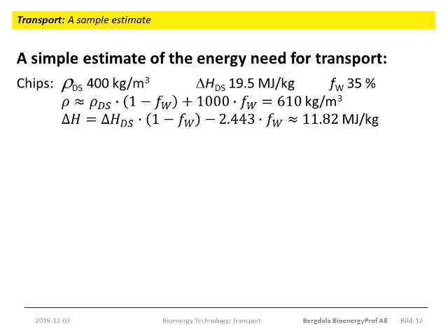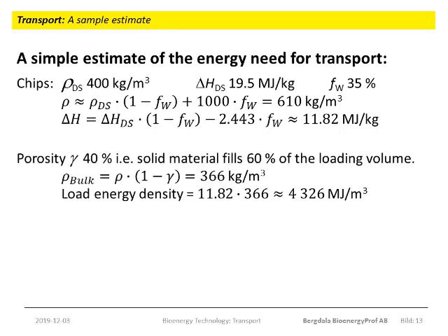Using these values, we can now estimate the density for the wet material, and we can compute the heating value. Loading a particulate material like chips will never fill the volume. There will always be holes between the individual particles. The porosity will depend on a lot of factors like particle size distribution, vibration, etc., but 40% porosity may be a realistic assumption. Using the porosity value and the solid density, we can now compute the bulk density.